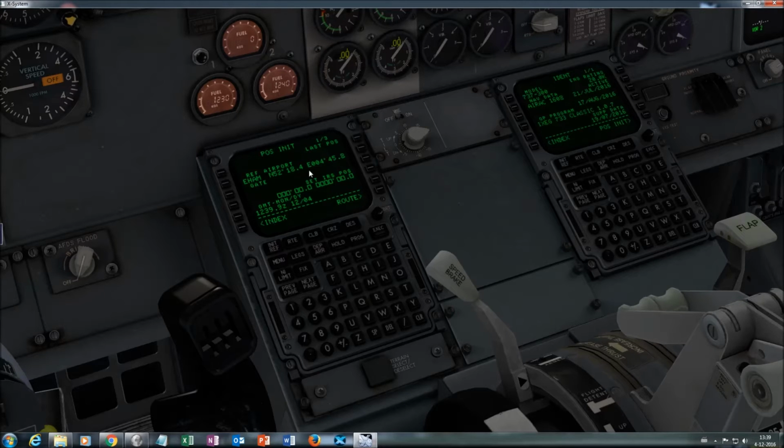And this coordinate is the general coordinate of the airport, but it is not necessarily the position of the aircraft. In fact, I think in 999 out of 1,000 times, this is not the current position of the airplane. And of course, if we are going to tell the flight management computer where the airplane is, we do want the coordinate where the plane is exactly and not this one.